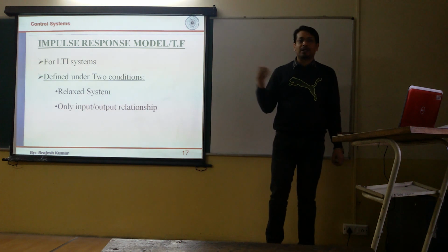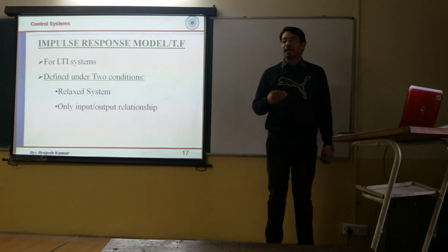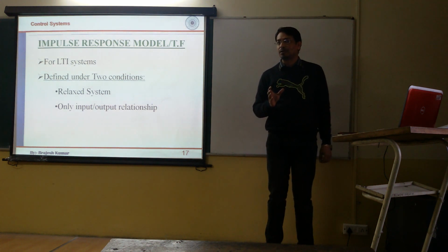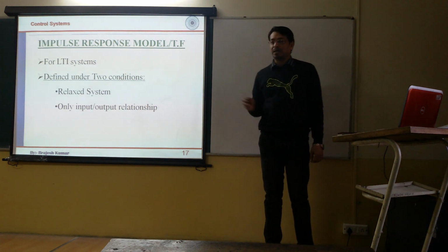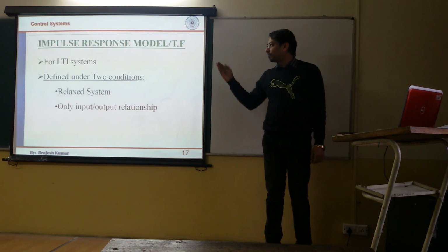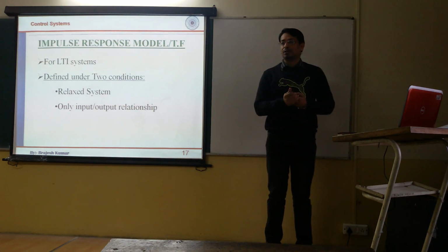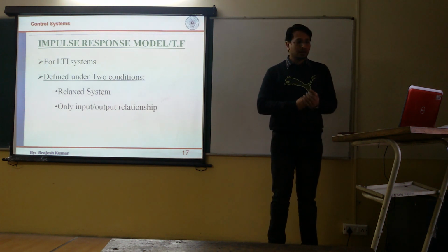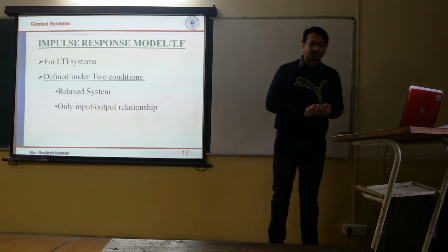By saying that this particular system is linear time invariant, I mean that the characteristics of the system are not going to change with time. Though the input can change and the output can change, the components of the system should not change with time. So this methodology will be applicable for such systems where, say, an inductor or a capacitor should not change with time. Then only you can apply your transfer function model or impulse response model.